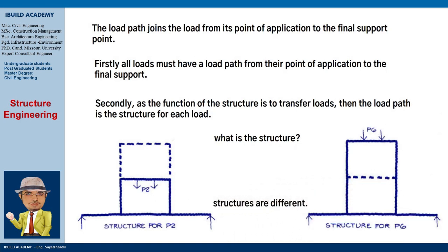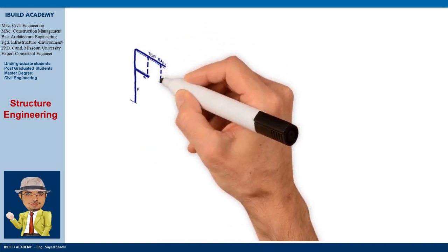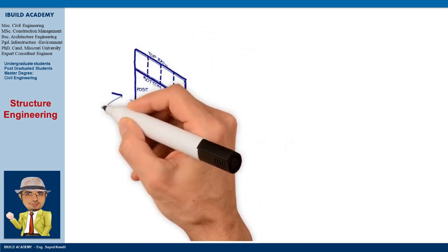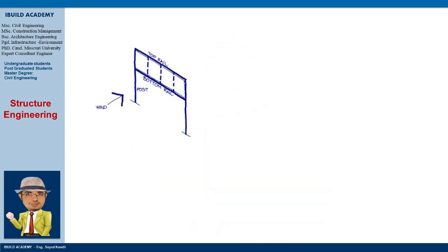The identification of vertical load paths for most buildings is relatively straightforward. Oddly, it can be quite complex for simple buildings, like houses. Not only do vertical loads need load paths, but so do horizontal loads. These loads are usually caused by wind. How does the signboard resist wind forces? The main wind load is caused by the wind blowing on the actual sign, and only the load path for this load is considered. This means the effect of the wind on the rails and posts is ignored.